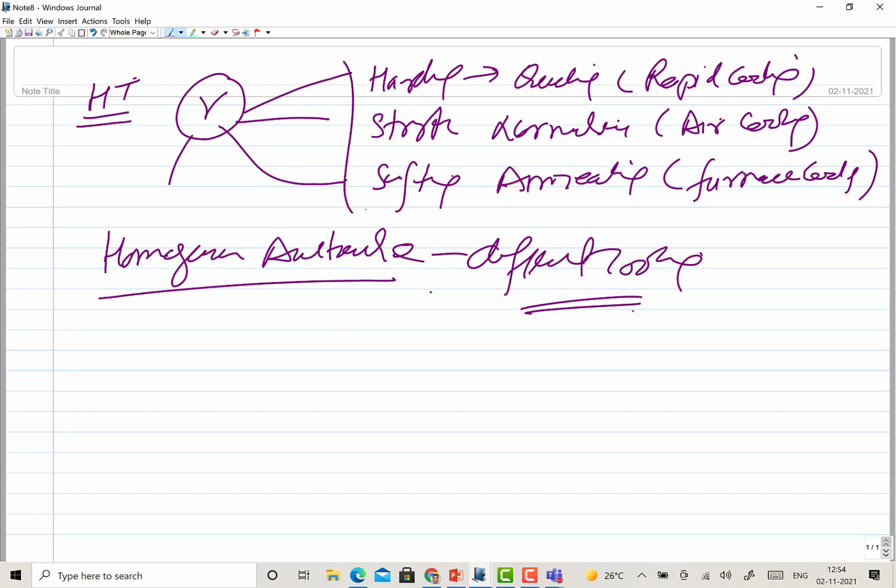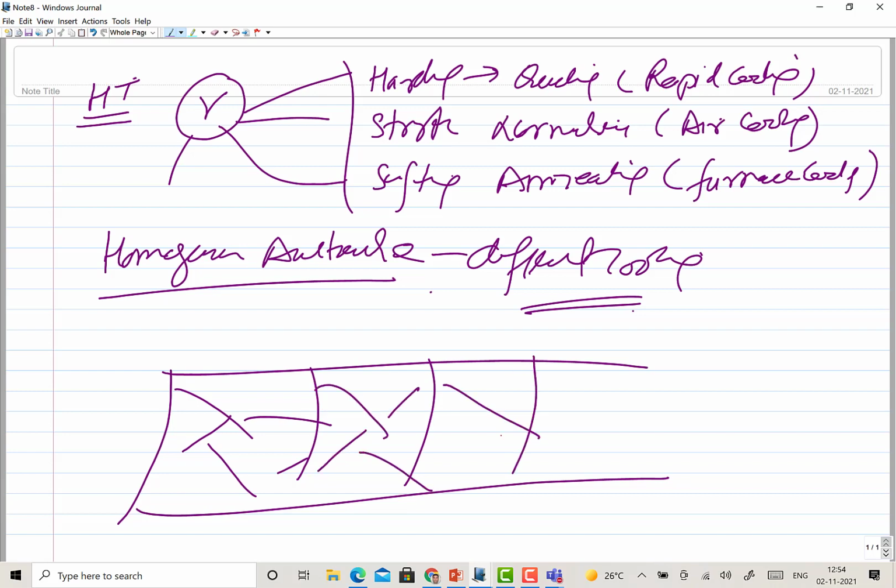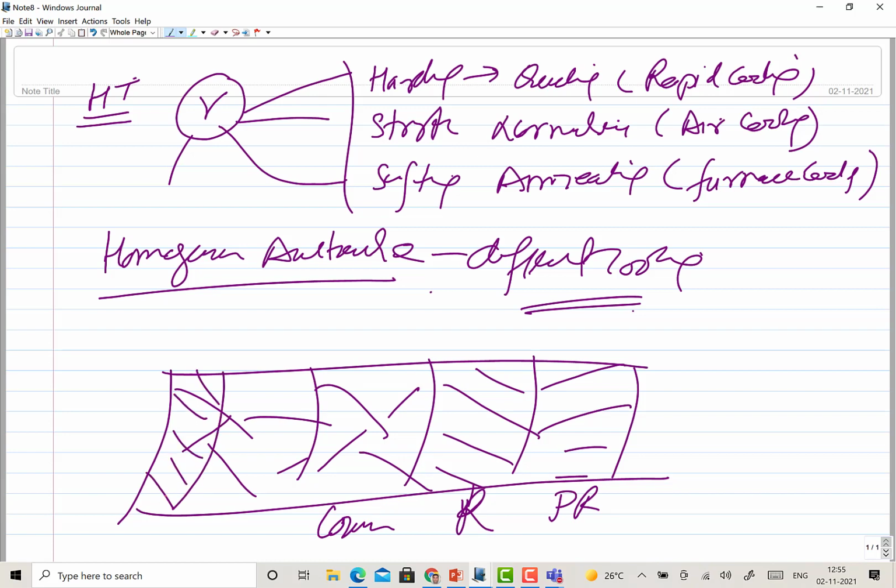This is where now you'll be coming across a variety of problems. This is the weld. Here you had one thing in your transformation. Here you had another thing. In the third zone you have something different. In the fourth zone you had something different. So now here you found the refined, the partially refined, the coarse grain, further coarse grain, and the partial melting zone, PMZ. So the coarse grain and the PMZ, these are the four zones.